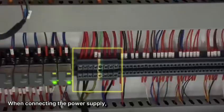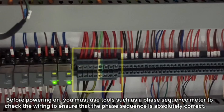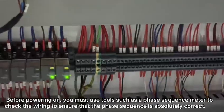When connecting the power supply, please connect the 3 live wires and 1 neutral wire to the corresponding terminals in sequence before powering on. You must use tools such as a phase sequence meter to check the wiring to ensure that the phase sequence is absolutely correct.